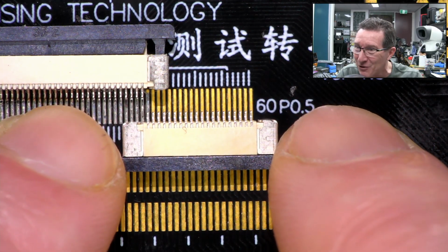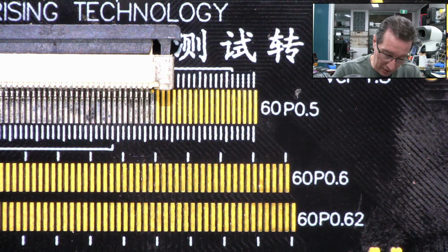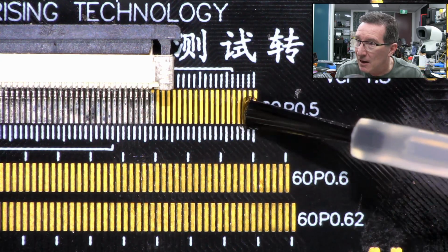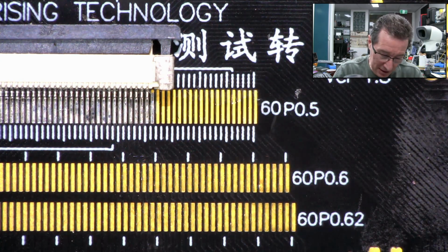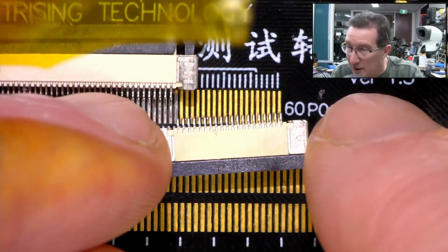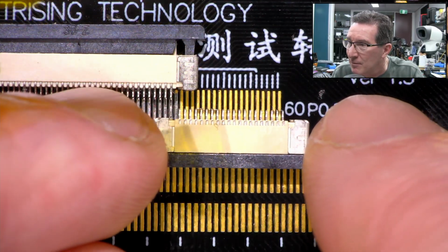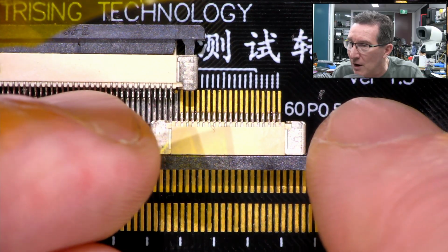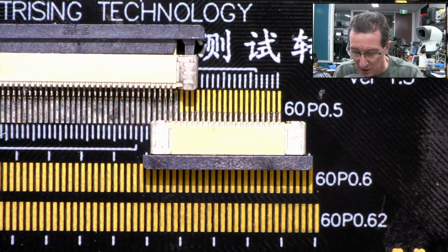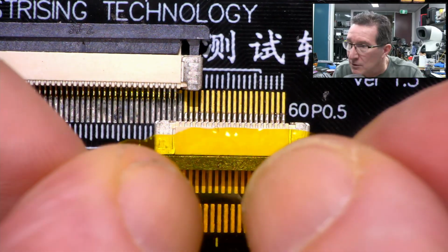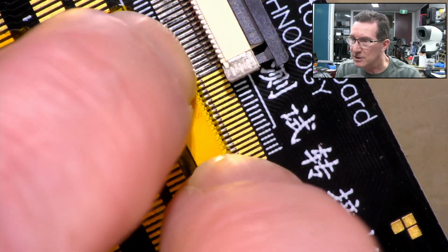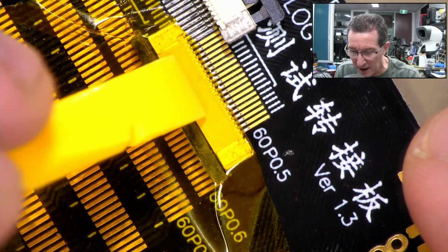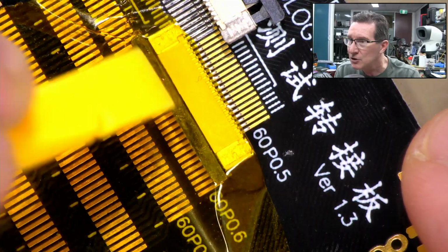So I'm going to solder that on. So let's solder this on. I'll just put down some flux. There we go. Bobby Dazzler. And we'll place this on here. And because these are really hard to hold, keep holding down while you actually drag solder, I'm just going to hold it in place with some Kapton tape. It's not going to sit flat, so probably have to put a little bit of downward pressure on it like that. But apart from that, we should be right.